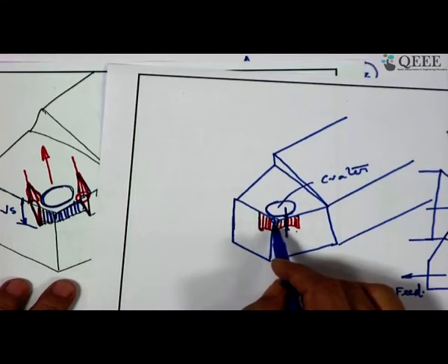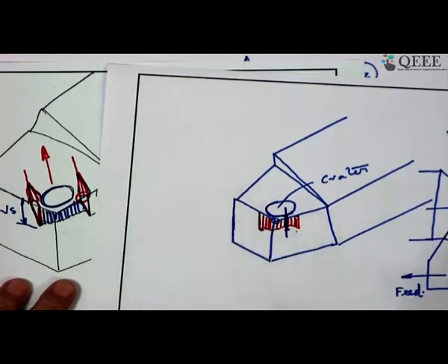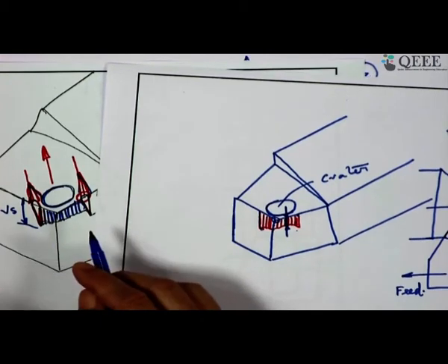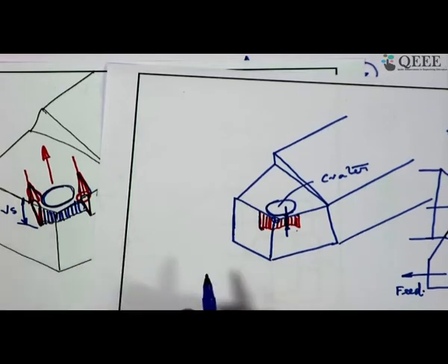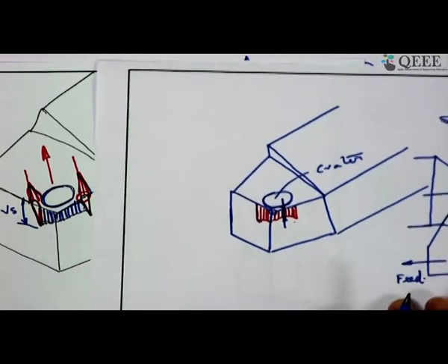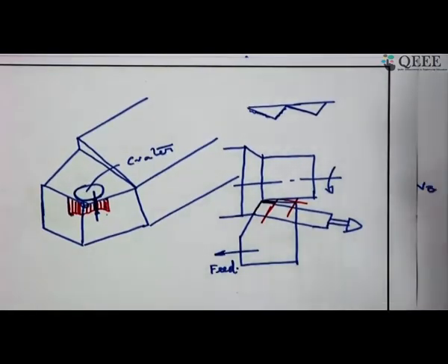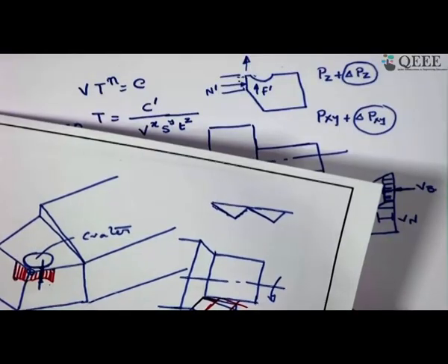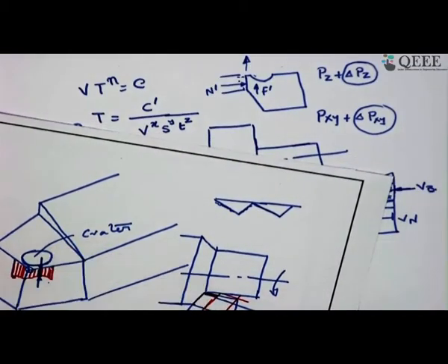So, this wear and the tip wear cause dimensional deviation, and this side wear, if it is a rough surface, then your surface finish will be severely affected. So, when we sum up these reasons, make a summary, we come to the conclusion why tool wear should be minimized, or we have to pay great attention to the tool wear, and there are various ways of controlling the tool wear. So, this is what we can say concerning the tool wear on the flank side, both principal flank and auxiliary flank.